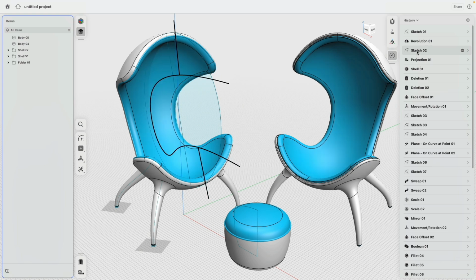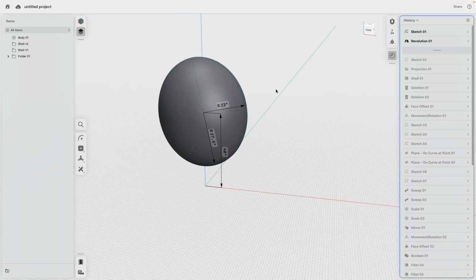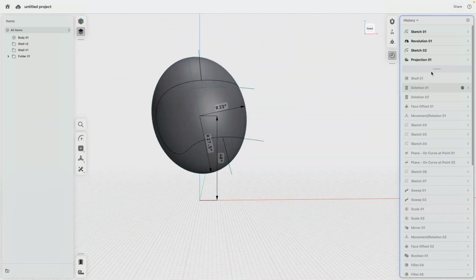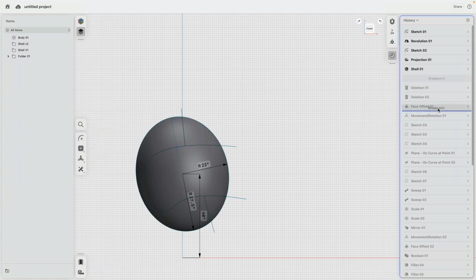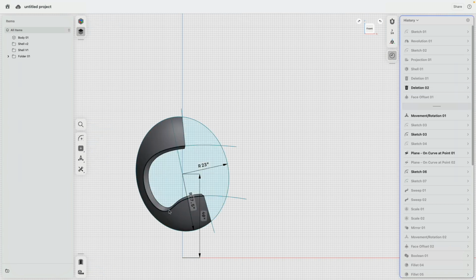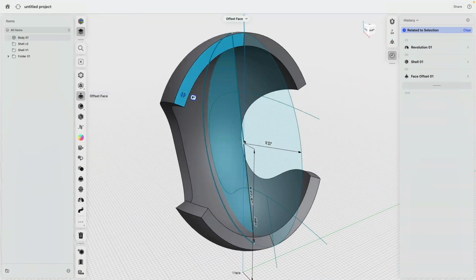After the first sketch, we will create now our basic body. We create the sketches to slice. We project actually this onto the surface. Then we will shell the design and then actually use the push and pull offset command to simply cut this space open. And look at that.